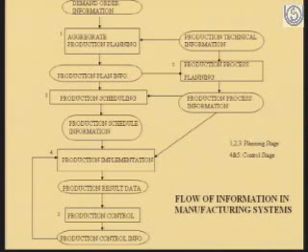And then we have production process planning. For production process planning, we require production technical information. Technical information means which route it will follow, that P, Q, R, S, T, and what time it will take. That will also work as an input to the aggregate production planning. At the same time, it will also work as an input for production process planning. From production process planning, we get production process information. That means how it will be manufactured stage-wise, operations-wise.